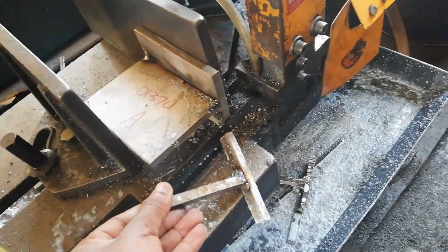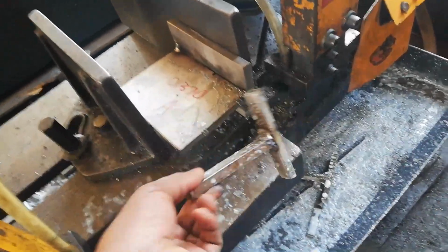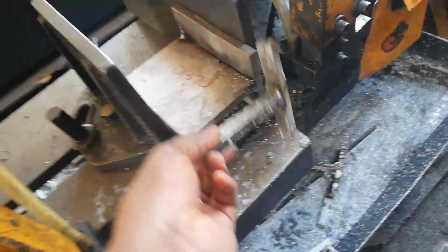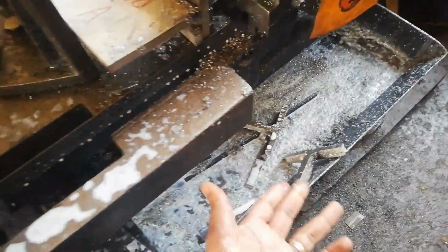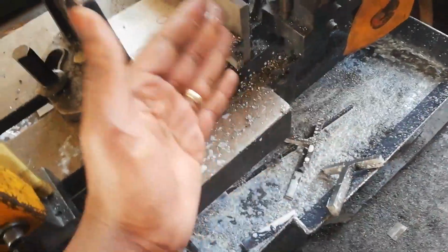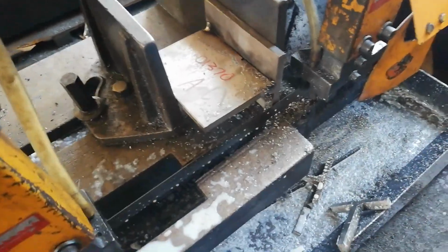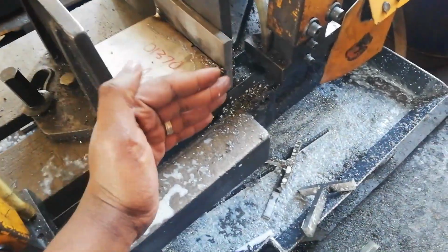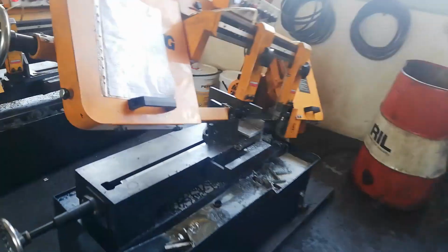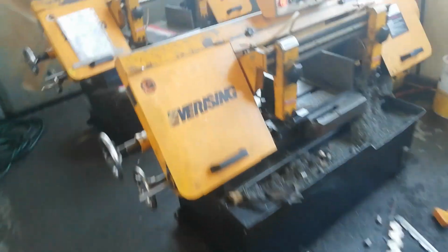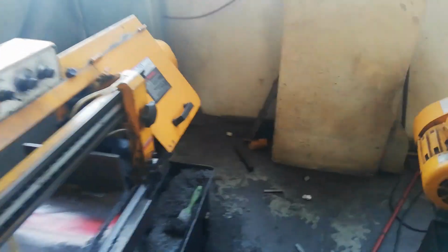As I told you about the part that's going to be discarded, this is an example of the part that will be discarded. So you discard something like 20 to 25 millimeter out of the sample that has been dropped, and then for the remaining part you cut either the macro and the fracture or macros only, depending on what the testing code is asking for.